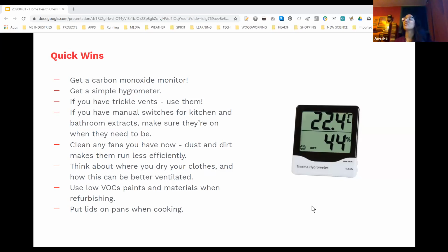So I'm actually in a flat at the moment in the Red Bricks in Manchester, and we did some home energy efficiency assessments on these flats. Because you've got less wall area, and in houses, wall insulation is probably a big area of heat loss. In a detached house, certainly in a semi-detached house and terraced house, the amount of walls exposed to the outside will be reduced. And certainly in a flat, you don't have many external walls.